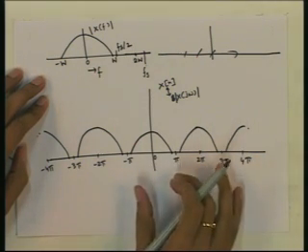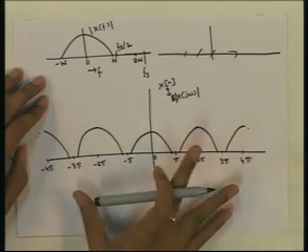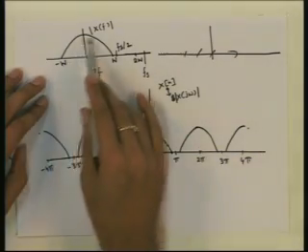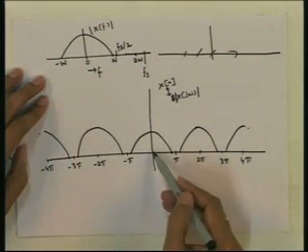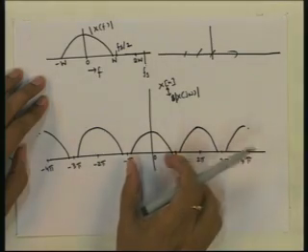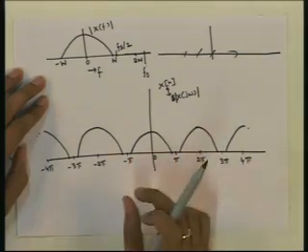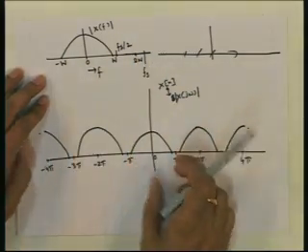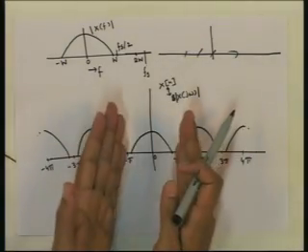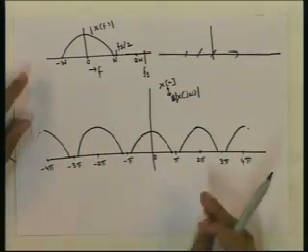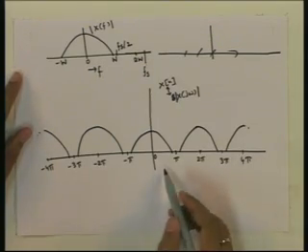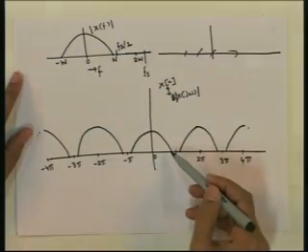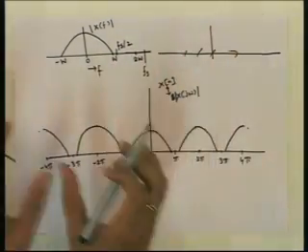Now, as we can see in frequency domain, the DTFT of the signal has this spectrum as part of it. So, this whole spectrum is still present in this signal separately. There is no mix up of these different copies. So, we can still recover this signal, it should be still possible to recover this signal from here, because we just take this part and do some processing and take this part and convert it to analog signal. So, we will see how to do it later, but we at least see that there is apparently no loss of information when we go from here to here. We get only multiple copies of this in disjoint frequency locations.